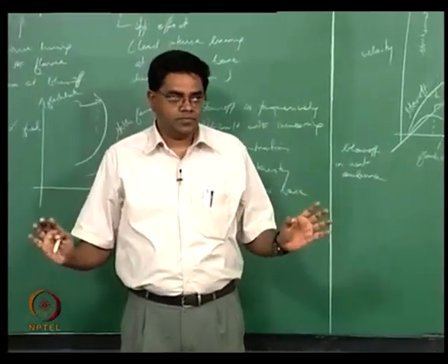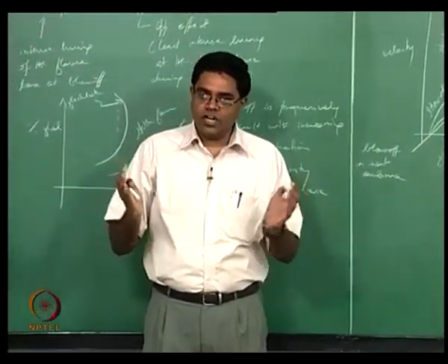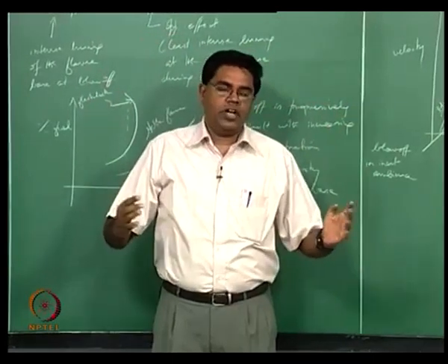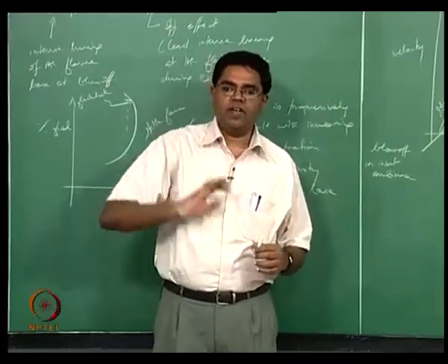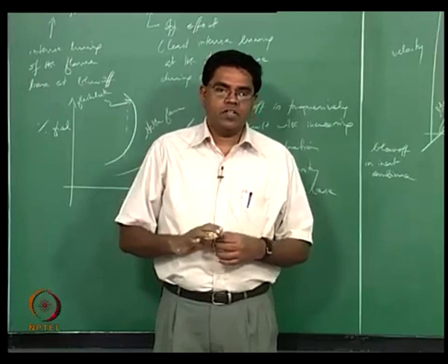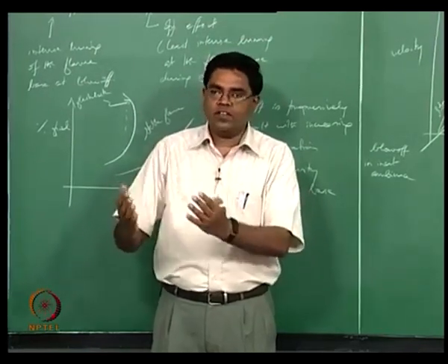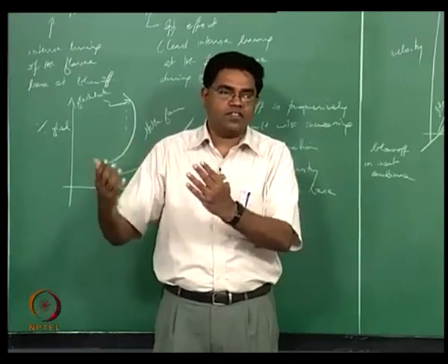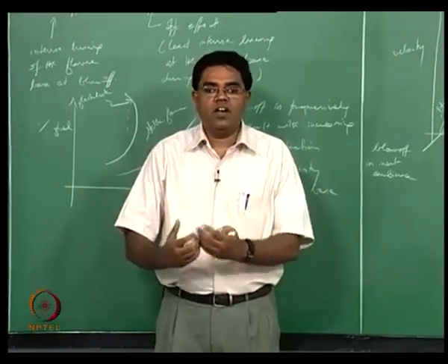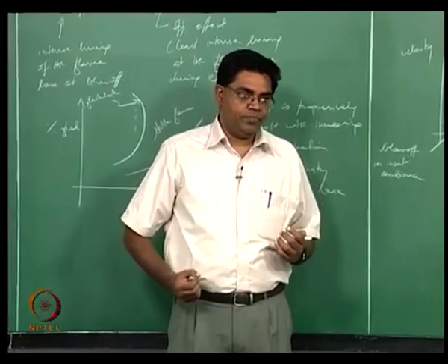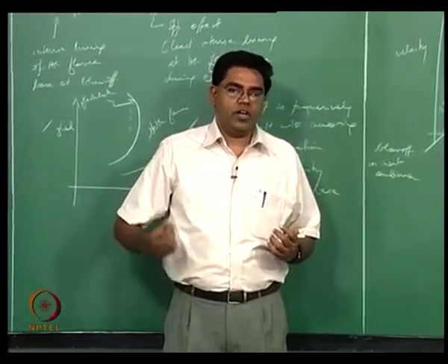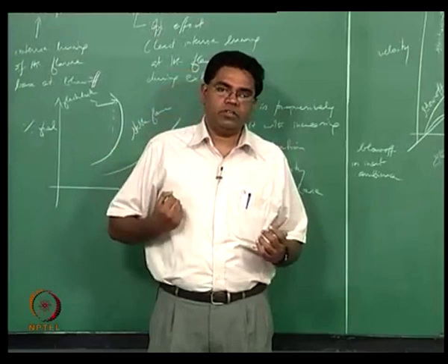This is typical, and so long as you have this diffusion flame envelope, it's a lot harder to destabilize this flame, because the diffusion flame is going to actually be there with the fuel and oxidizer, or the excess fuel and oxidizer, mixing all the time, and it doesn't really have to propagate against a flowing mixture, a flowing reactant mixture.